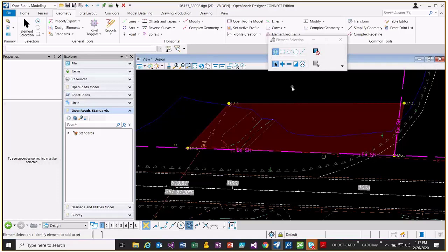So I had initially set those as construction elements, so in theory they wouldn't plot, but in talking with Ray, we did not make those construction elements. So it's intended to be used as the underlying element, not anything that would be shown on the plan, so that level will be turned off if you don't want that shading. What we are going to show on the plan is the taking area, and that's a standard highway easement line.